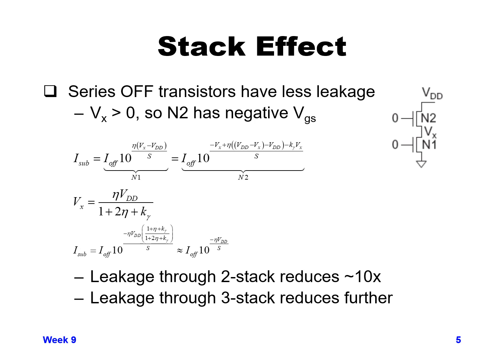It's probably better to simulate it and get a more precise number on a given process technology, because every process technology is going to be a little bit different in leakage, based on your VT and a lot of other effects. But definitely having a stack of 2 can reduce your leakage by a fairly dramatic amount as long as both devices are turned off.